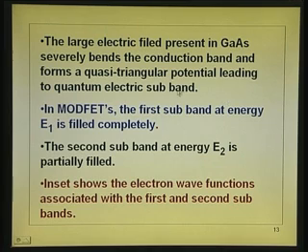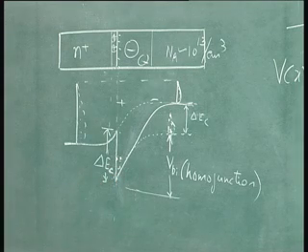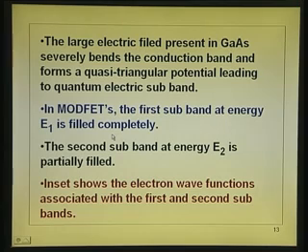So, the large electric field present in the gallium arsenide means the band bending is more. In fact, we have given enough explanation on that. Band bending is more here, therefore, electrons are knocked up there. So, in MOSFET, we will go back to this afterwards. What we are telling is there are two levels there, E1 and E2, which you showed.